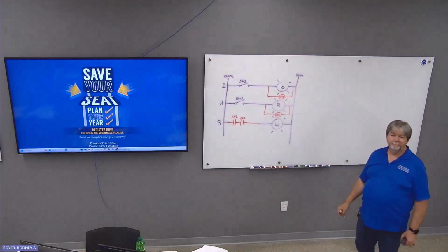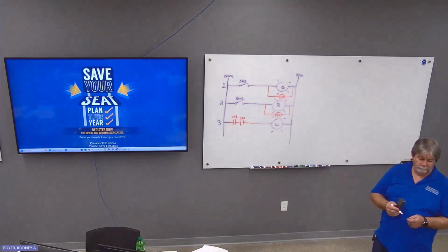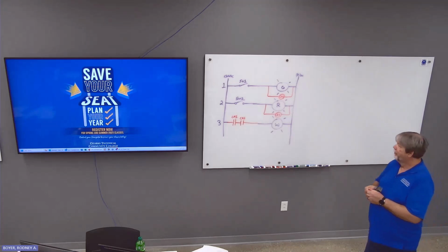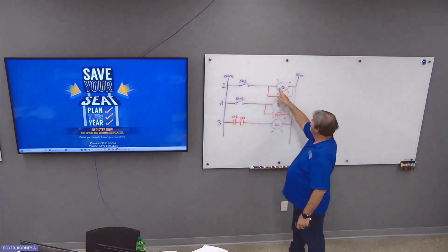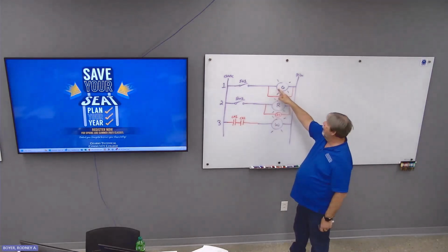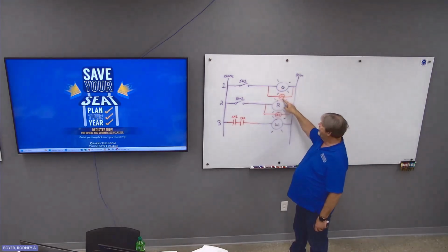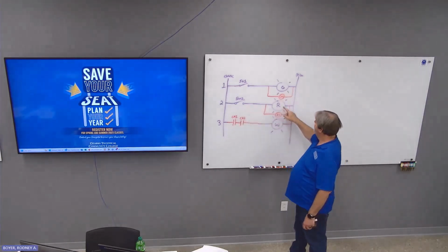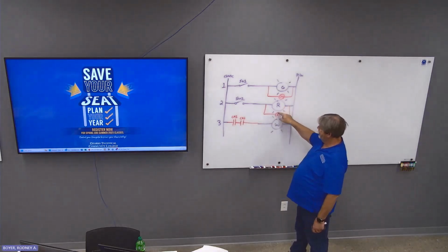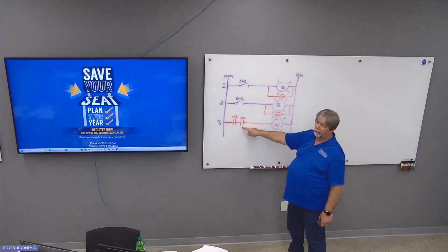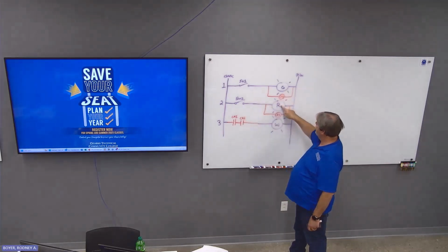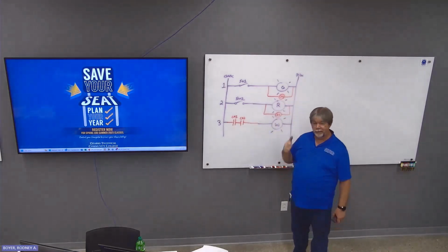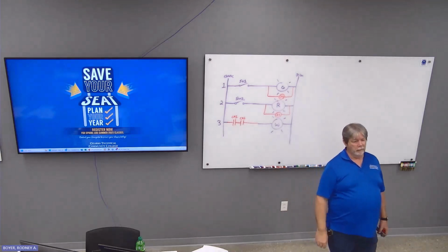Does that fix it? I think it still keeps the green and red on. That keeps green red on. Close the switch 1, green, you're going to receive power and CR1. You're going to turn the green light on and close that contact. Push switch 2. Red light's going to come on, energize CR2, and close that contact. But do both of them, green and red both turn on, both CR1 and CR2 energize. Close these 2 contacts, white turns on, but it's still got red and green. So that's not the right solution.